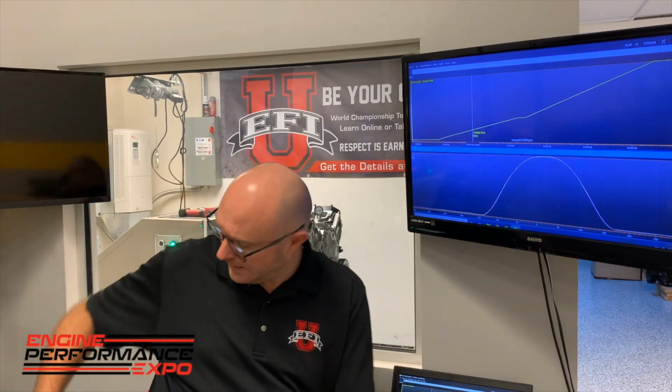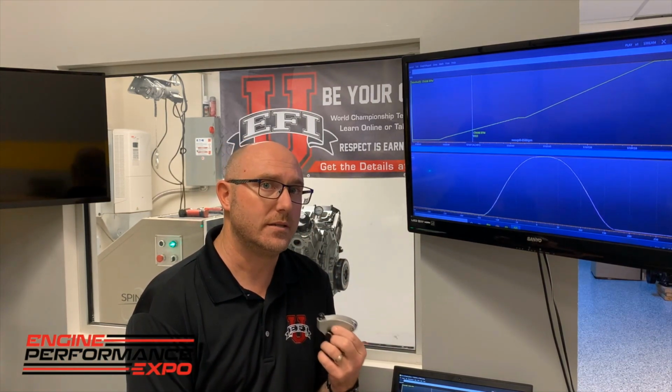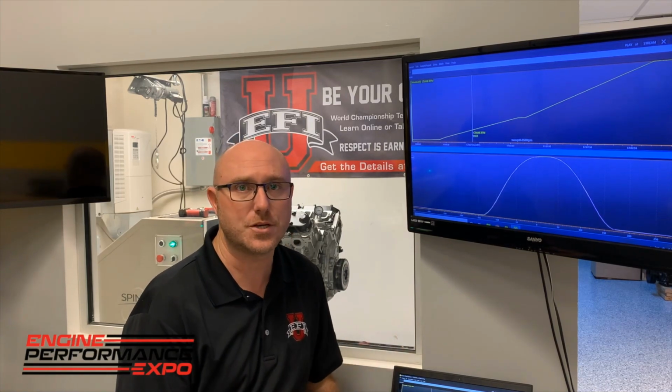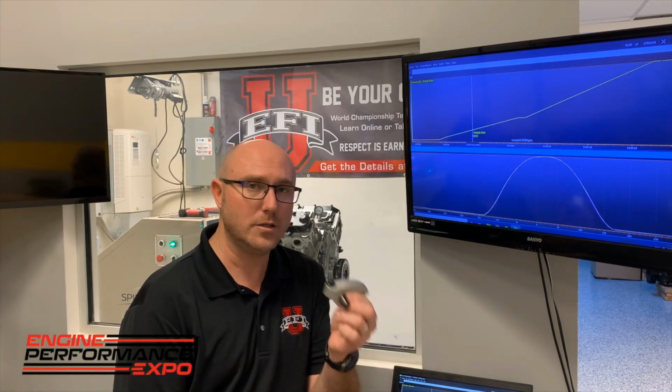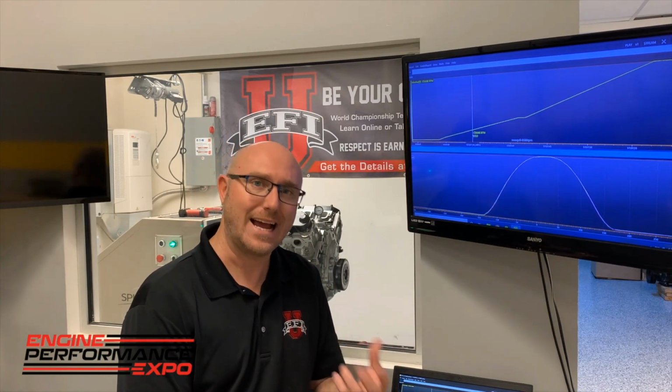If I take a rocker arm, for example, and I got one that's made out of aluminum, there could very well be a difference for the same camshaft and same lifter and same pushrod in the engine. There could be a difference between my aluminum one and if I change it out for a steel one of the same size and design. We would be able to see that throughout this lift curve because we can measure it in real time dynamically.